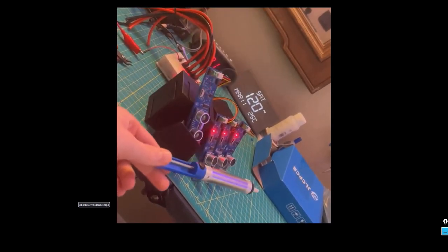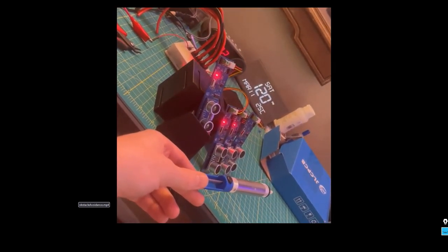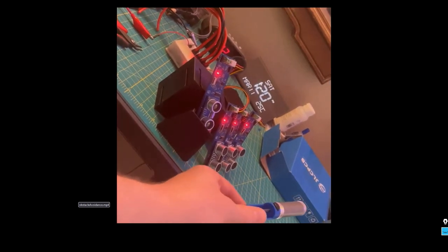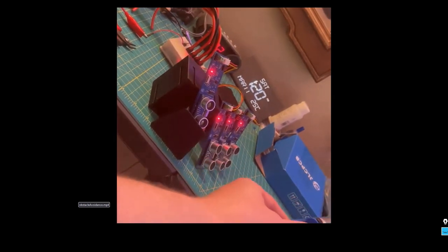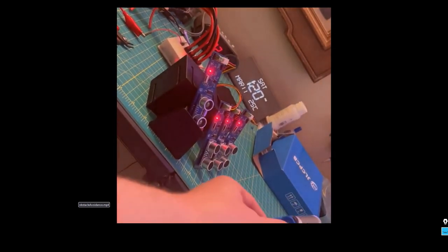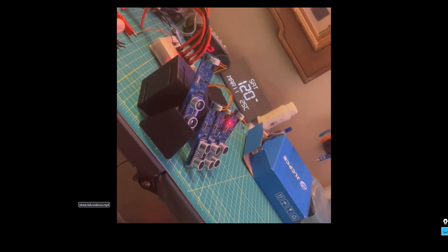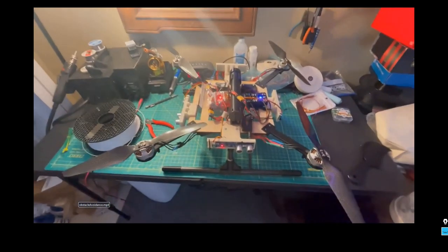Dr. Ritchie informed us that the noise, or what I thought was noise, was most likely due to crosstalk between the ultrasonic sensors, given that these boards were facing in the same direction and placed in close proximity to one another. And this theory was pretty much confirmed when the boards were actually attached to the drone on their respective sides, each facing 90 degrees away from one another.